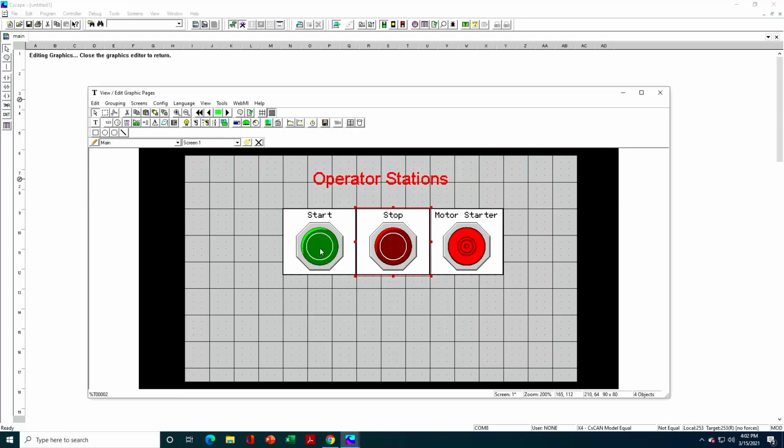Okay, so we've got a start button, which we've assigned to T1, or I'm sorry, assigned to T2. And if I don't remember what was assigned to it, I can hover here and it shows me. If I hover here, it should show T3. If I hover here, it's Q1. And the reason why this is Q1 is because this is the same bit that turns on the real world wired motor starter. It's the same bit that's going to cause this light to turn on. Okay, so that's why that does have a real world IO point.